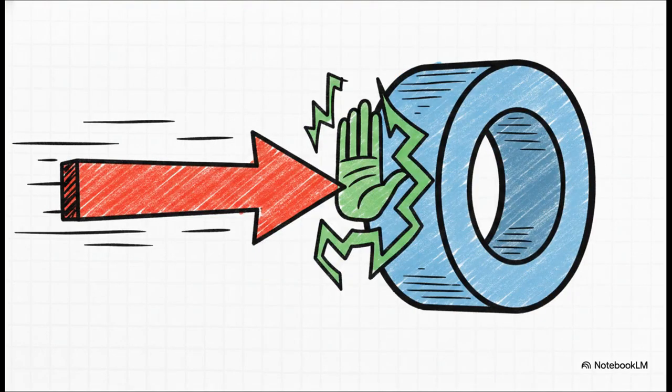Okay, let's build up the math that makes this happen, step by step. First up, we've got flux linkage, which we represent with the Greek letter lambda. That is simply N, the number of turns in our coil, multiplied by the total flux, phi. And that's the flux threading through all those turns, not just a single loop. Next, we define self-inductance, or L, which is measured in henries. This is just your flux linkage divided by the current producing it.